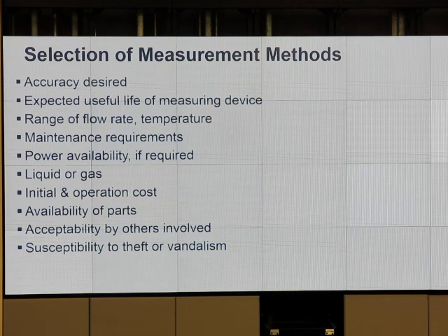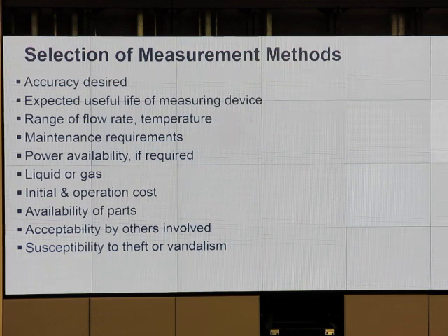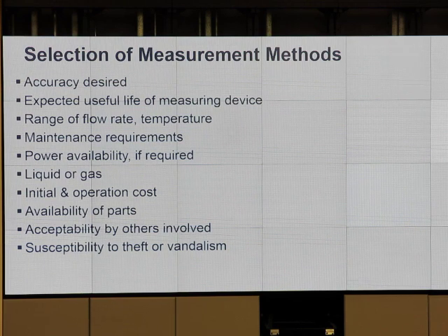For each flow meter that we use, we need to know where the error is coming from. In what case it can do the measurement, in what case it cannot do the measurement. For example, the electric charge that you just saw, they do the measurement with water, right? If you have oil, there's no electric charge. The molecule is non-polar. Does it work? It may or may not work, okay, or it may work differently.